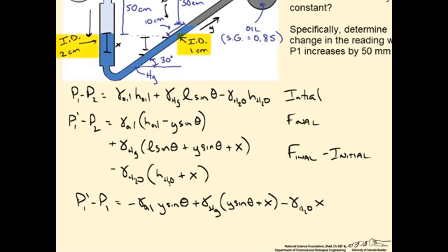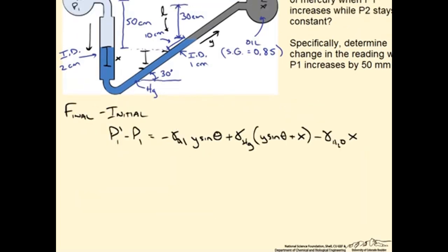We happen to have the inner diameter of both of those tubes, and so just doing a mass balance of fluid on the left side for mercury and on the right side for mercury, we could figure out the relationship between x and y. Since we're dealing with just one fluid, we know that the mass balance is also going to be equivalent in this case to a volume balance. So if we take the cross-sectional area on the left side and multiply that by the height change, x, this must be equal to the volumetric change on the right side.